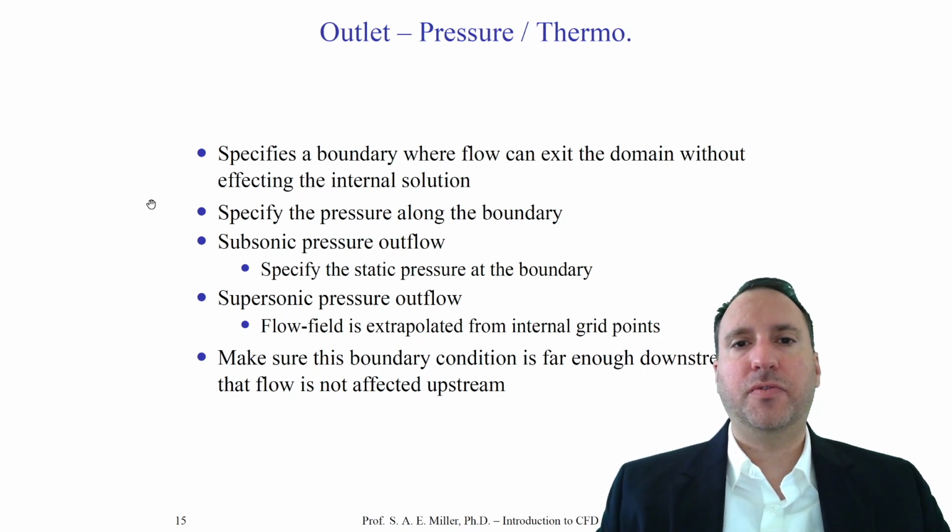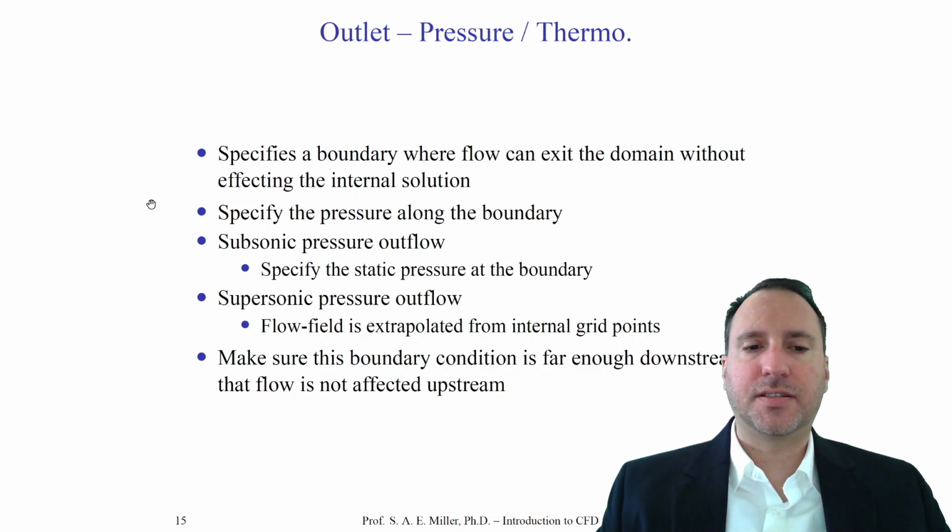So you'll have to move your static pressure boundary condition far downstream from some object which is creating a transonic flow. This is critical, or else your solver will crash.